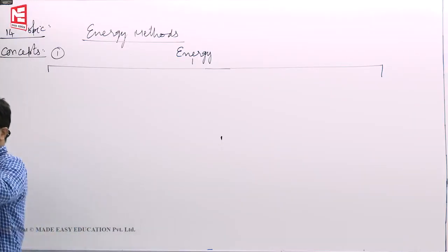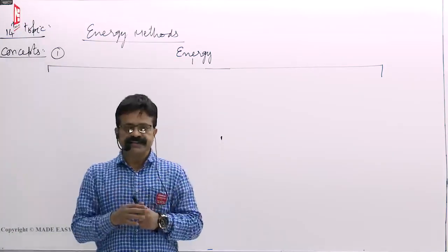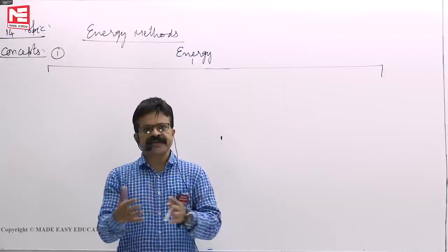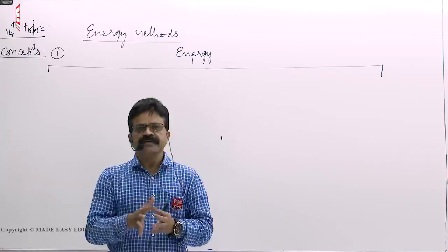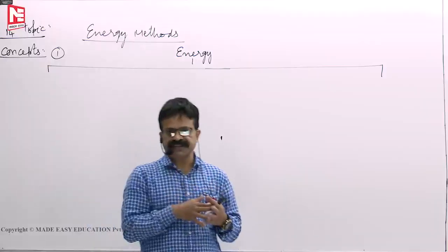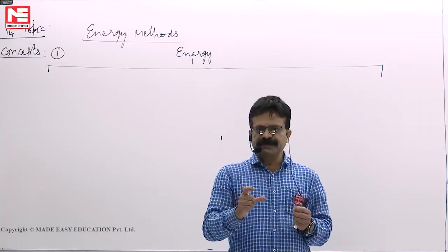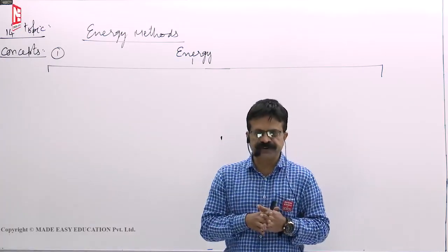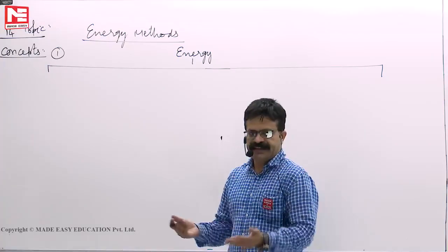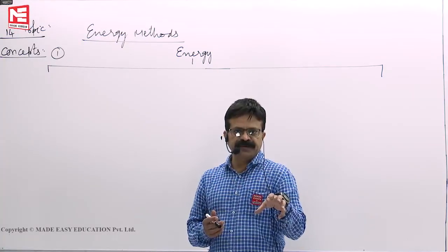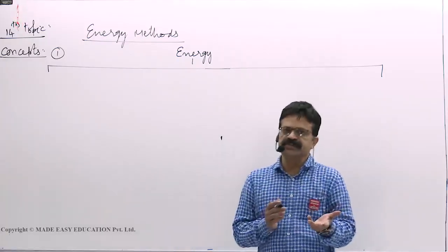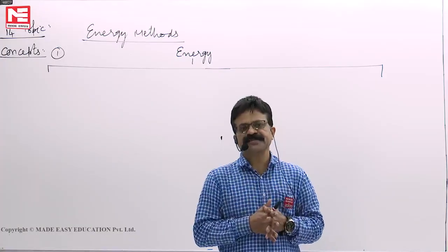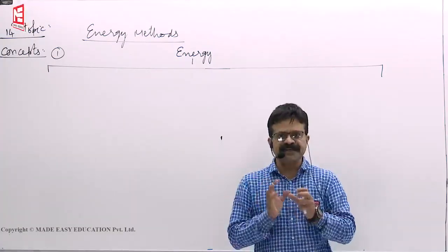I have told you when we took the strain energy chapter: gradually applied load, suddenly applied load, impact loading, and also Castigliano's theorem 1 and 2 I have given. Based on Castigliano's theorem 2, we found the deflections in the trusses, relative displacement, absolute deflection, and rotation of a member for statically determinate structures, from the strain energy stored in the members. PKL by AE we have taken, then we used the same strain energy stored in the structure for a frame. We found the displacements also, integral of M x m dx by EI.